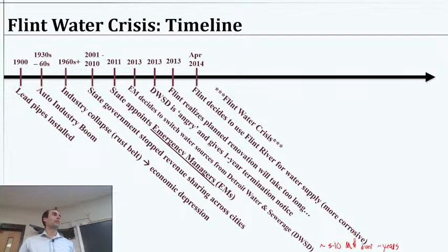It sounds kind of like a small thing, and if you notice, we talked for almost 3 months now about water treatment, and we didn't really talk too much about it directly. So it's not a major component in our minds necessarily, but it's a major component of maintaining the distribution system. And really, we would call it orthophosphate, which is just phosphate, PO4 3 minus. Some form of phosphate would buffer the water and help prevent corrosion, and it doesn't take a lot.